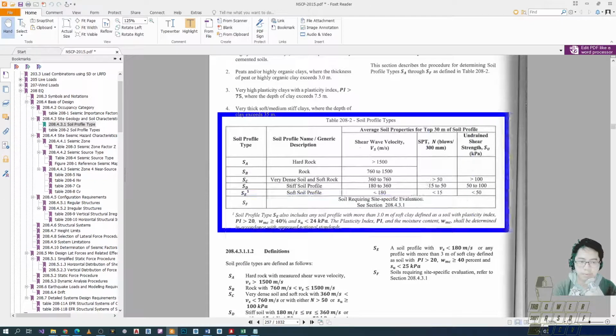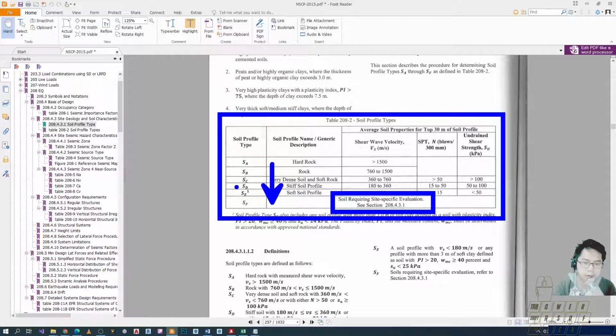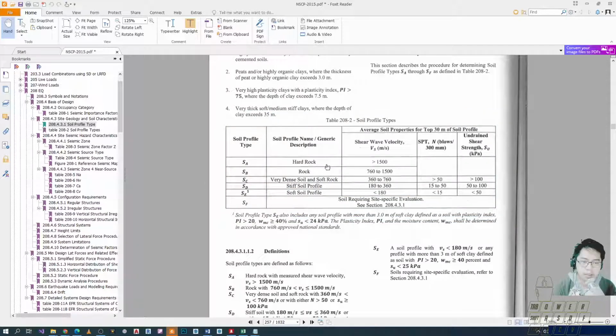So, ito yung pwede natin gamitin. You can use them as your basis para ma-identify mo from A until F. Hard rock hanggang lalambot ng lalambot. F, kailangang may special tayo na consideration. So, let's just assume a relatively stiff soil parameter. So, D. Let's use number 4.